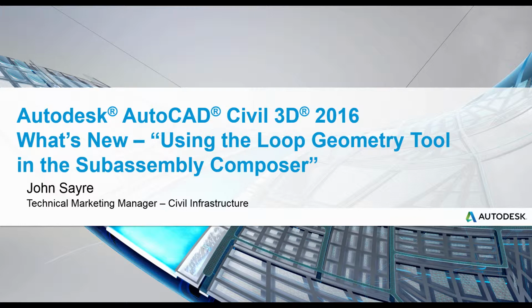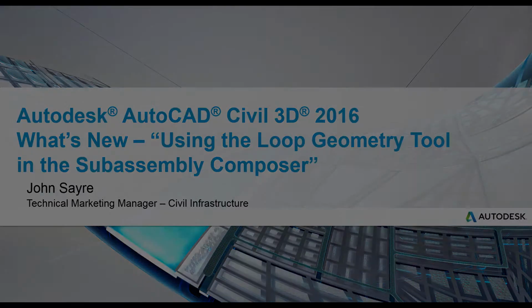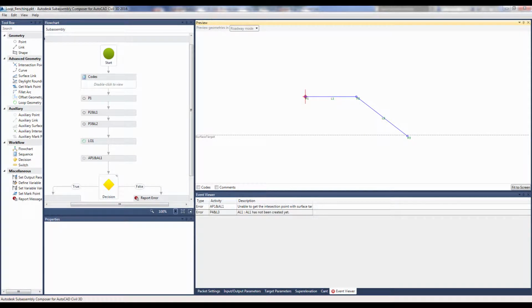Today I would like to talk about one of the What's New features in AutoCAD Civil 3D 2016, using the Loop Geometry tool in the Subassembly Composer. The Subassembly Composer has been updated such that we can build custom subassemblies more easily. Users now have access to a new loop geometry tool for repeating specified links until they reach a surface target or until they are repeated a specified number of times. For example, this tool can be used for benching along a roadway.